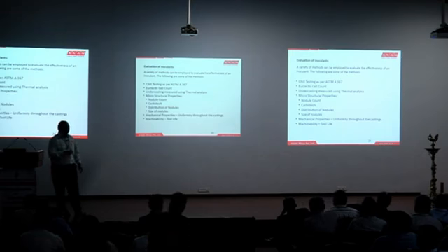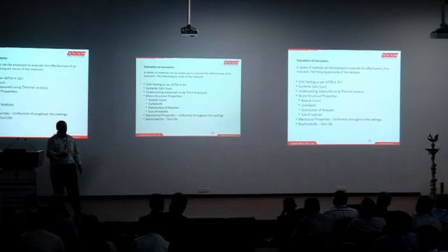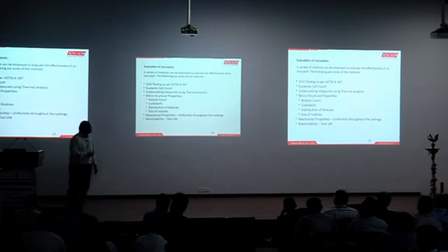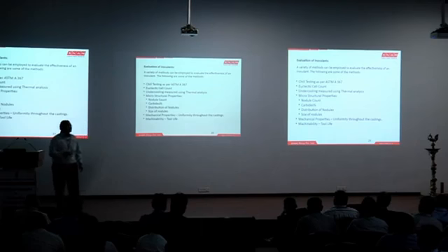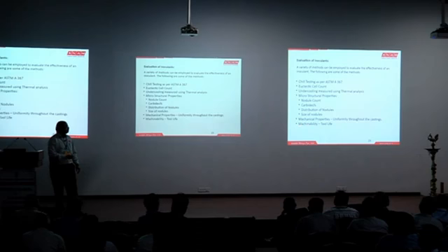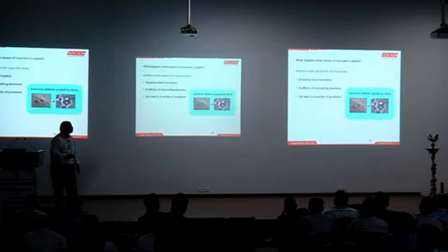Nodule count or type of graphite flakes and amount of graphite flakes. Distribution of nodules, the size of nodules. In the same way in grey casting, distribution of graphite flakes, type of graphite flakes and the amount of graphite flakes. Mechanical properties, uniformity throughout the casting. The catch is uniformity, and what inoculation can give you is uniformity only. Machinability, tool life, are the output of all these previous parameters.